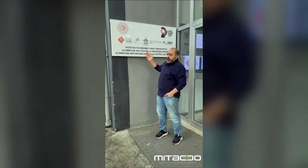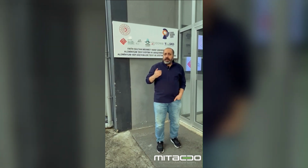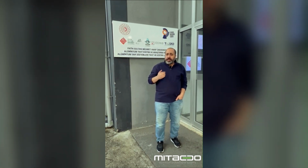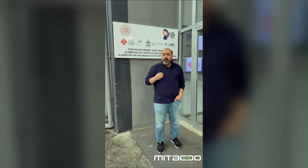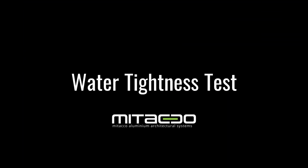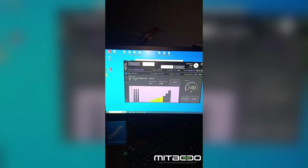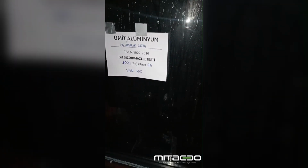We are at Fatih Sultan Mehmet Vakif University, Estelle Laboratory. Here, we will perform air, water, and wind tests of our facade systems, sliding systems, door and window systems. Our target is Class 9A 600 pascals. We will test it up to 900 pascals. 3 pulses are applied 3 times quickly, up to 660 pascals, not exceeding 100 pascals per second.